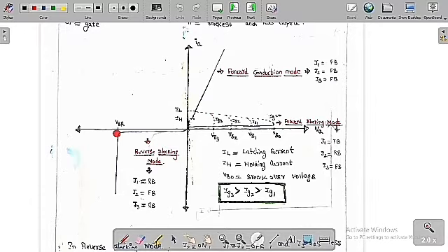After the breakdown voltage of the junctions J1 and J3, these are also going to conduct, but now a huge amount of current is going to flow and the SCR is going to get damaged. So this is the reason we are not going to operate the SCR in the reverse conduction mode. Only in 3 modes we are going to operate the SCR, which are forward blocking mode, forward conduction mode and the reverse blocking mode.